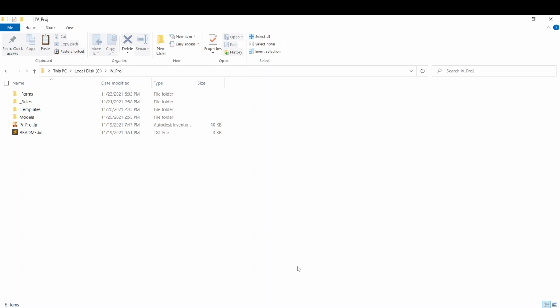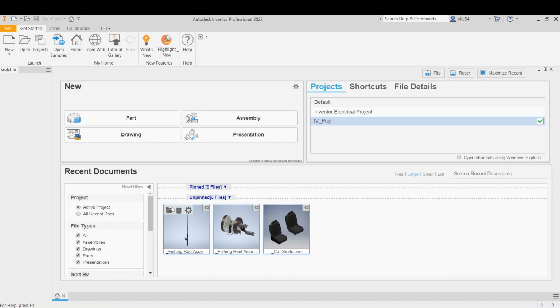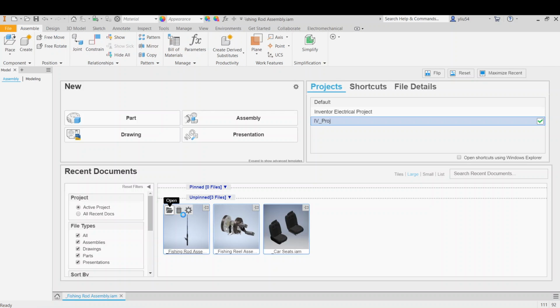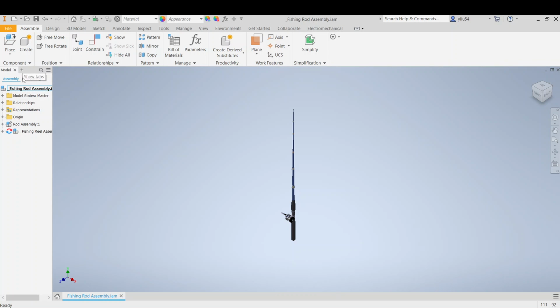Now go back to your Autodesk Inventor software. Open a 3D model to navigate into the iLogic browser. It is easier to set up the drawing automation iLogic along with a 3D model. Now, find the iLogic browser. If you couldn't find it, it's probably hiding here. Go to Global Forms. Right-click, open containing folder.